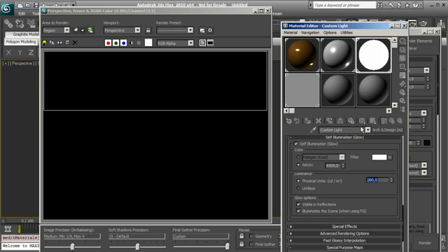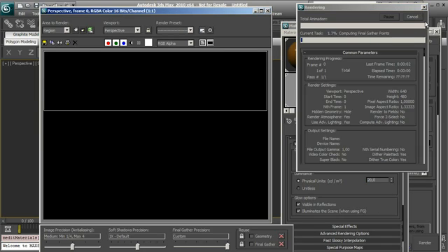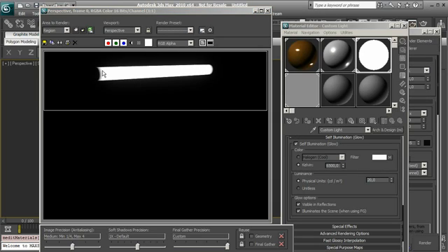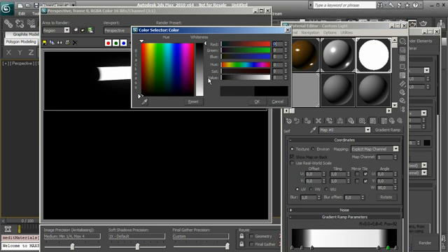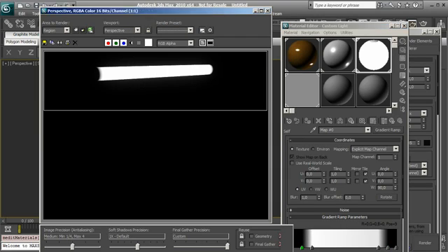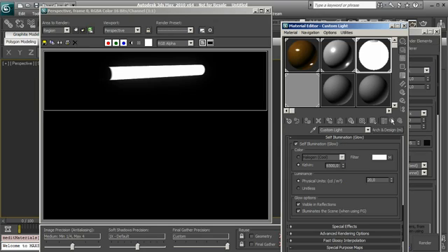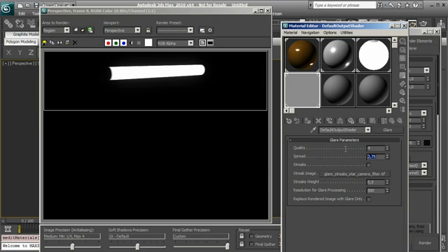And let's try to have less luminance, so let's try with 20, and you see that we have light coming more after. So let's use something like that, black and black. Let's render again, and you see that we have light coming more later. Okay, so we can change the spread.